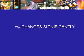So this drive has this bad feature that if the supply voltage decreases, the speed of the drive is going to decrease, and this is again a property of the DC, separately excited DC motor, that for torque changes the speed changes are negligible, but for supply voltage changes the speed change can be significant.